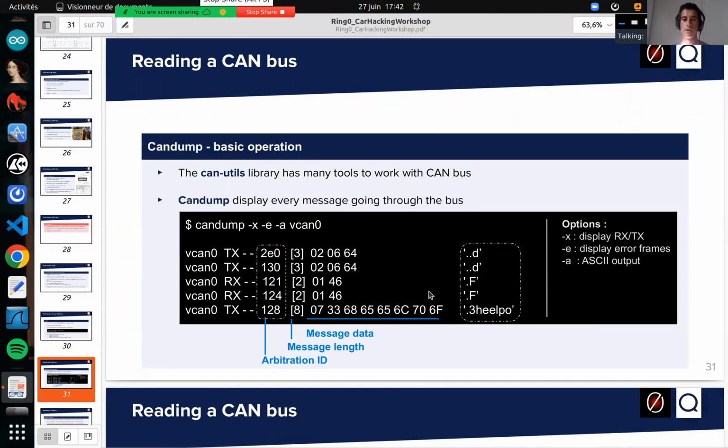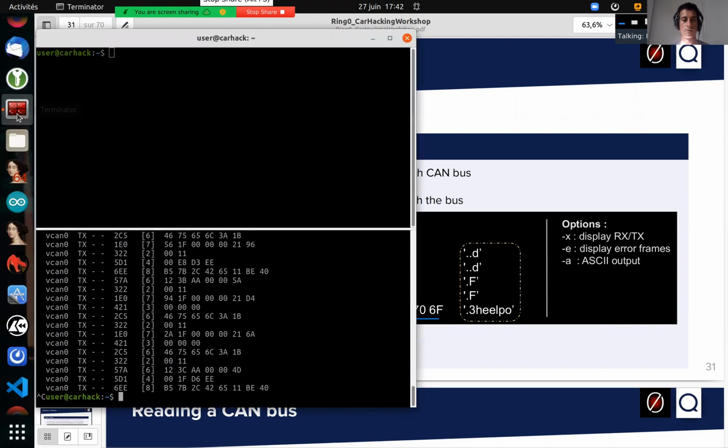On our virtual machine, the simulation is very easy because very few messages are broadcasted. On a real vehicle, you will have plenty of messages. And I forgot to say that CAN data are sent periodically. For example, the ABS reads the speed of rotation of each wheel and computes the speed of the vehicle. So the ABS will send the speed of the vehicle every X milliseconds.